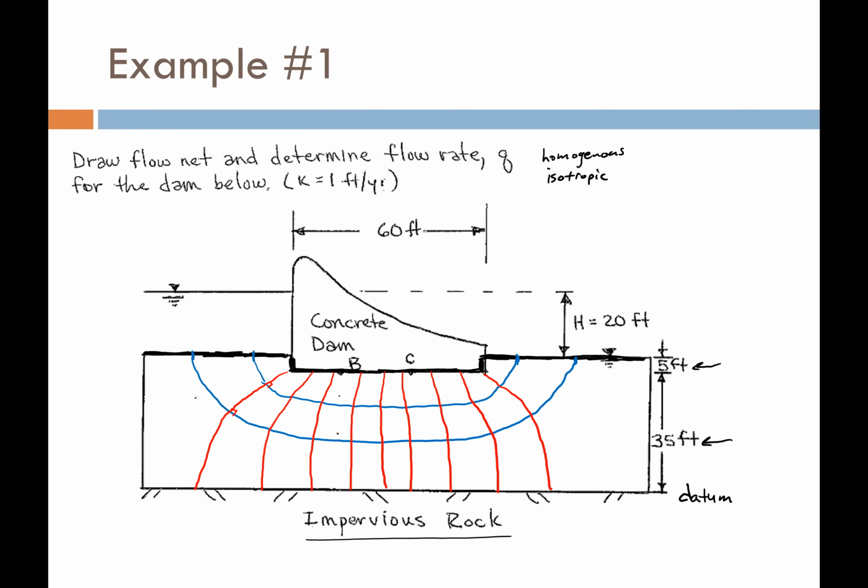Okay, so I would go back and I would start erasing some of these equipotential lines. I would maybe identify some places where it might need some work. So for instance, this element right here doesn't look very square, so I'd probably go back and work on that a little bit. So a lot of students go, whoa, Dr. Frankie, what about these corner elements here where I'm circling? Those don't look square at all. Those are freaky looking. Yeah, they are.